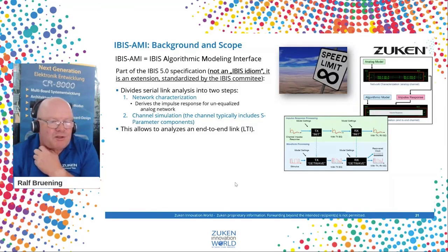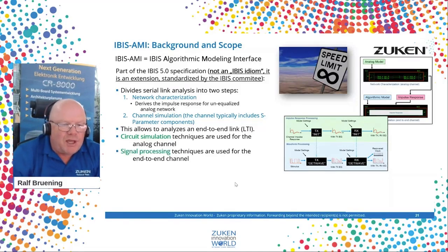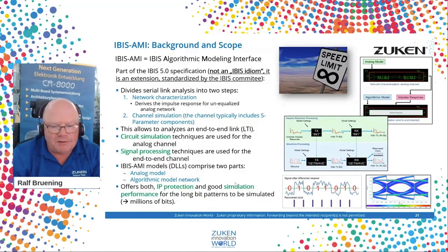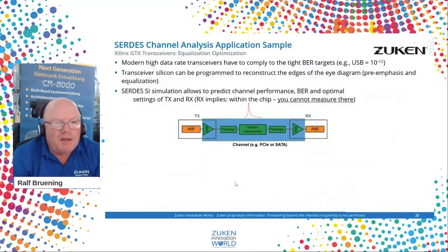One of the preconditions is that we have linear time invariant systems, LTI, but that's what we have with such a SerDes link. So that's a combination of different techniques: circuit simulation combined with signal processing, and it gives you an eye diagram. And that's what we would like to get, an eye diagram which is reliable in a fast way. It offers the IC vendors the nice thing that it protects the IP, because nothing about how the whole thing is operating within the chip is revealed to the end user. And we are able to simulate pretty fast, as mentioned, millions of bits in a few minutes.